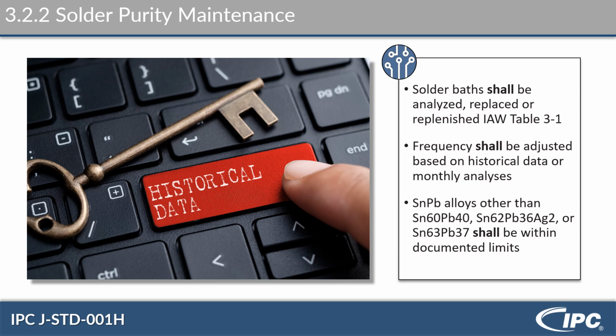But say it hasn't been cleaned in a month and you get there and there's way more gunk than there should be, you may say, maybe we should clean this every 2 weeks until we figure out what's causing this contamination.